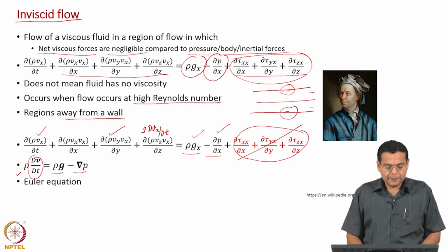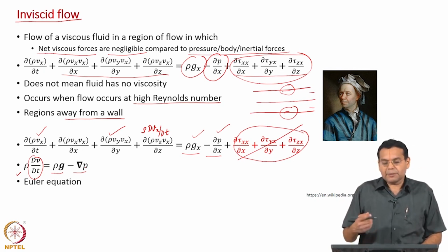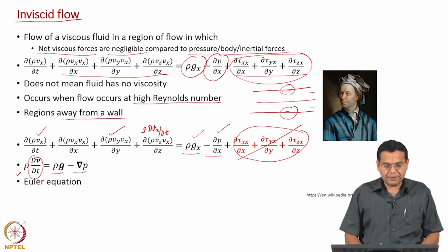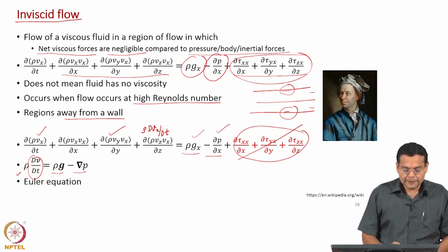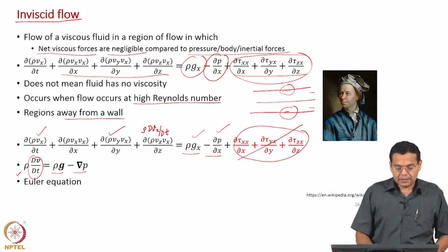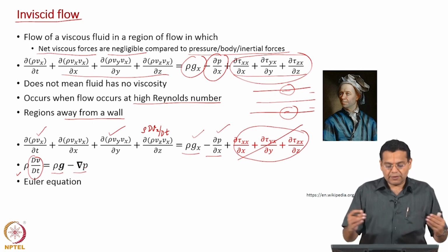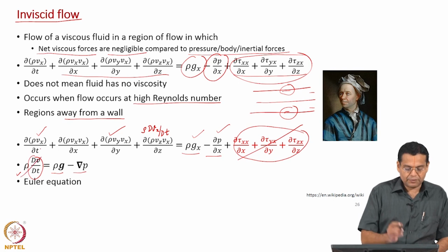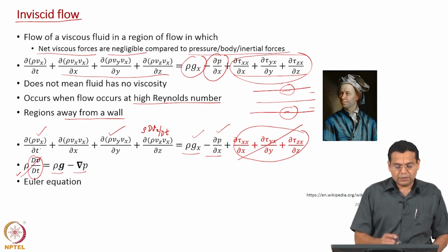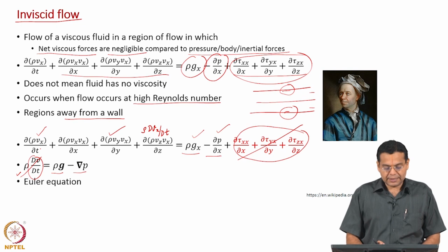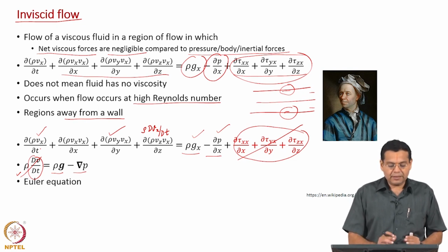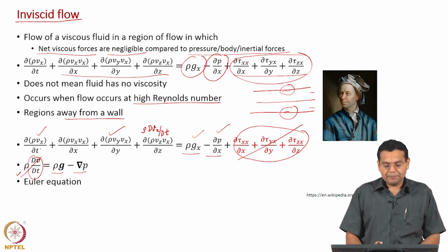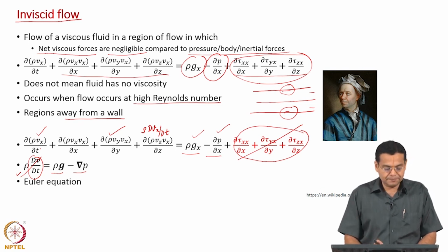What do we mean by that? We derived the all-encompassing linear momentum balance and then the Navier-Stokes equation as well. In terms of application we are slowly evolving. The first level of application, the fluid was at rest, so you did not have the left hand side, that was 0, and you had only rho g vector and the gradient of pressure. Even that could simplify to only the vertical direction, okay.